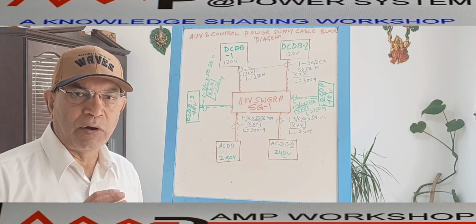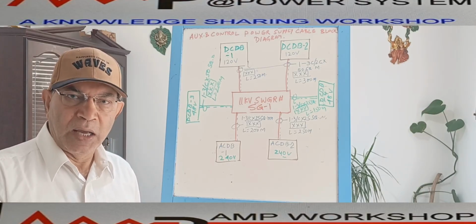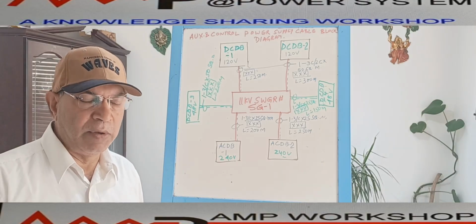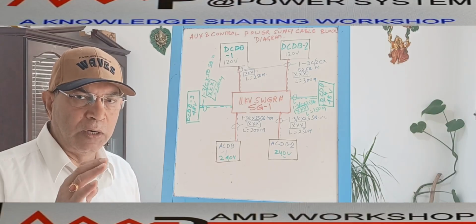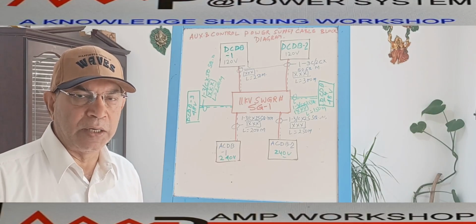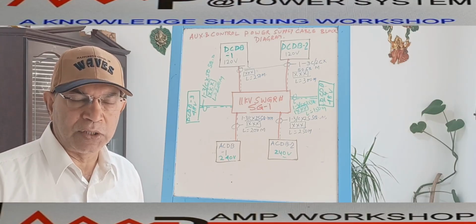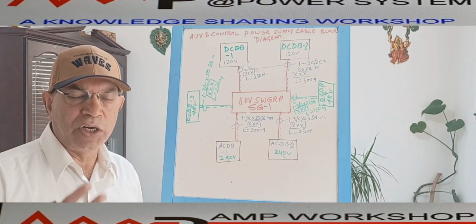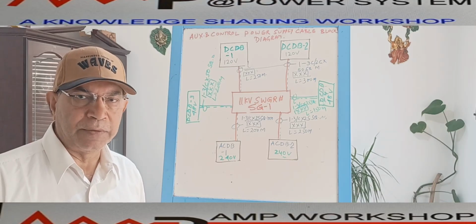The power section mainly contains the circuit breakers and isolators, CT, PT. If it is a full height panel, it will be the bottom part of the panel, and the top part of the panel is mainly the control and protection section, where the control relays, protection devices, various switches and auxiliary relays are mounted.